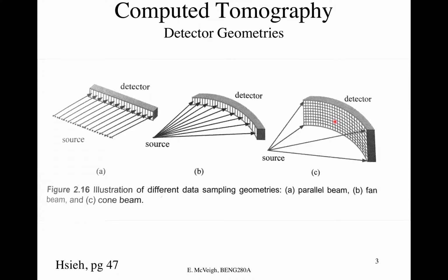Bring down the sampling rate. The maximum sampling rate is fixed for a particular device. So the question is, can we bring down the sampling rate? Yes. Our sampling rate is fixed by this separation, but we can average these neighboring pixels, or dexels, together, and that will bring down the sampling rate.